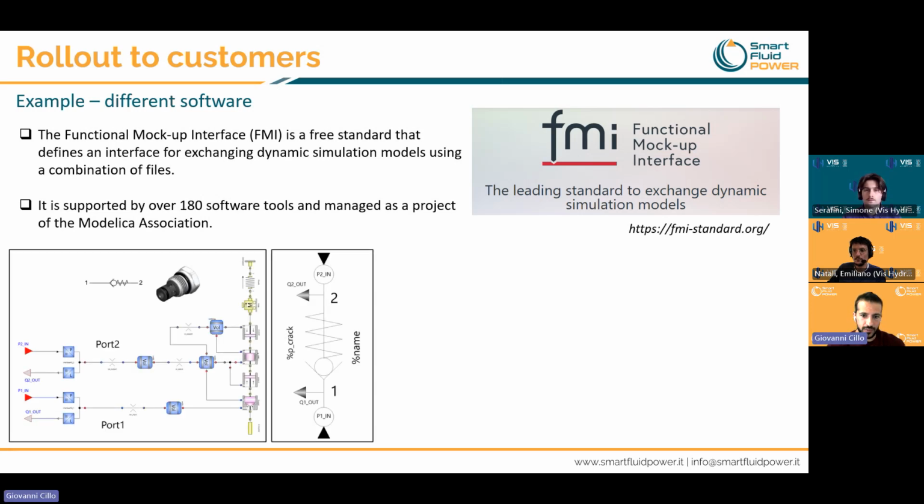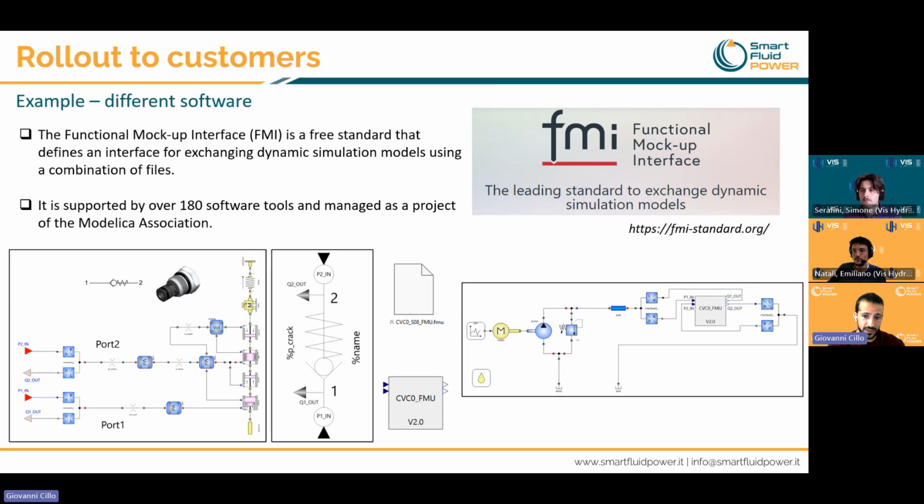Here as well, it is possible to decide which parameters and variables the user is allowed to modify or visualize. The FMU is then integrated into the customer's model through standard interfaces that convert the exchange variables into signals compatible across different environments. This is necessary because to enable co-simulation between different software tools, connections are based on dimensionless ports. This makes the setup slightly less direct, but also highly flexible and compatible with a wide range of environments.